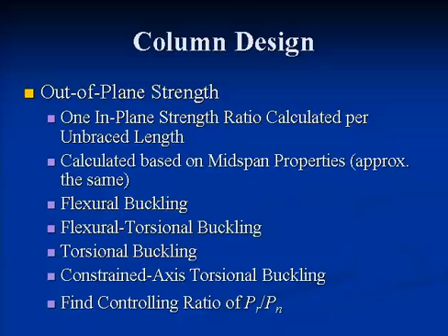Out of plane strength based on the unbraced lengths, based on midspan properties, doesn't vary much. RY is pretty much the same. If you look at the deep end or the narrow end of an unbraced length, it doesn't change much.